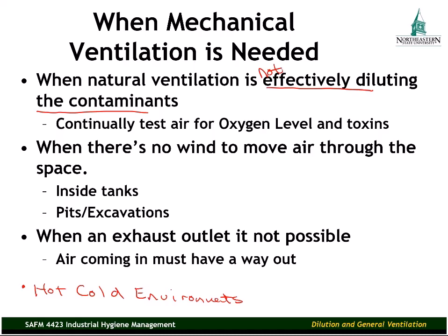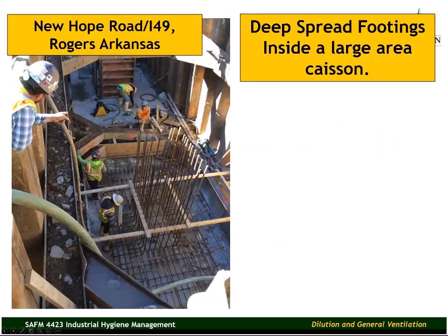Or maybe you work in an area where it's 15 degrees in the winter. Every day it's 15 degrees in the wintertime. You can't just open the windows in those environments and maintain the safety of your workers. That's a situation where you may need mechanical ventilation systems. Mechanical ventilation systems that will treat the makeup air. They either warm it or cool that makeup air as it enters the workspace. This is a kind of situation where you may need to consider mechanical ventilation.